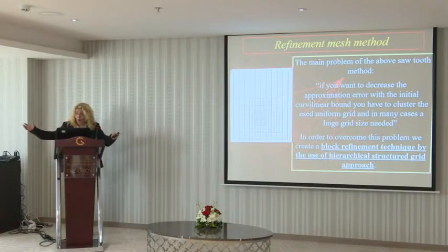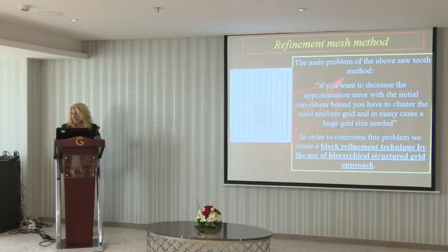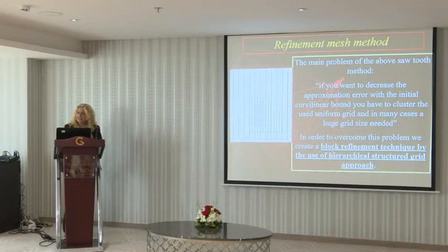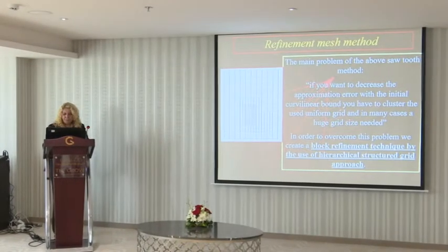However, if you have a long length of a pipe, the cells that are created are huge. The number of cells that you have to solve the equations is too many. Definitely, you need a refinement technique. Again, in order to simplify the technique, we use a block nested technique as the one that you can see here. We refine at the points of interest using rectangular grids.